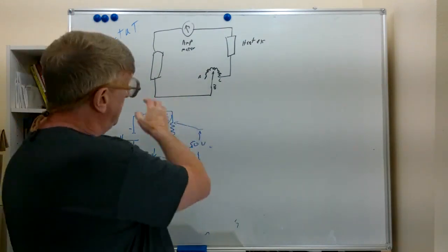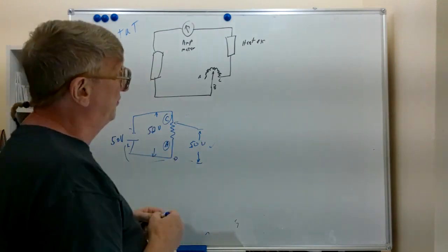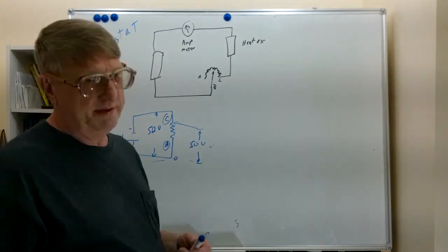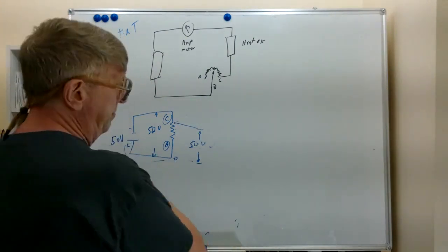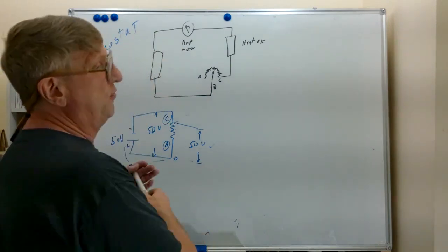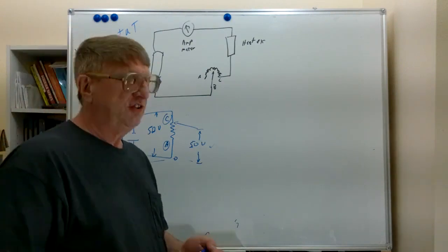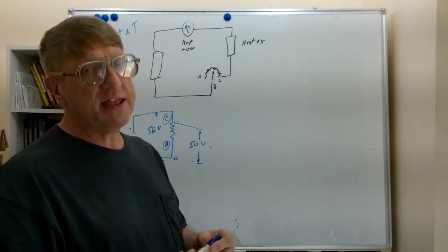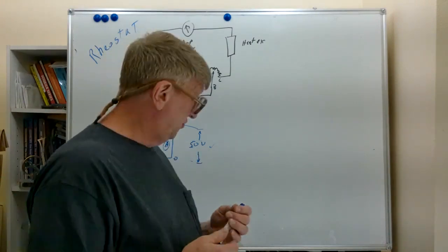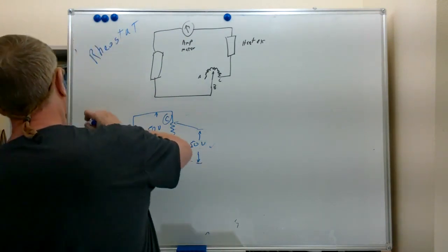Here in the potentiometer case, we're using the physical variable resistor to pick off more or less of a signal, maybe setting the bias on an amplifier, maybe picking off how much volume you're taking from one stage of a radio receiver to the next. Where in the tone control situation, we are actually varying the resistance to vary the tone response of the tone control. So this is a potentiometer circuit.